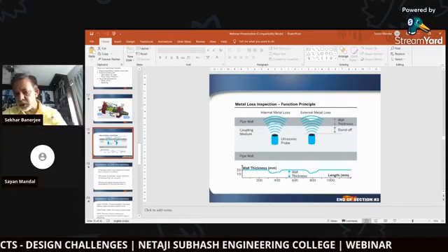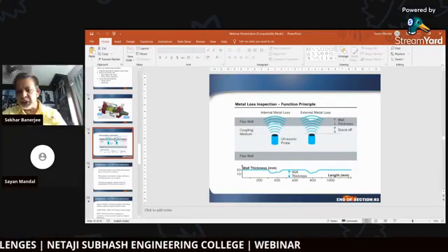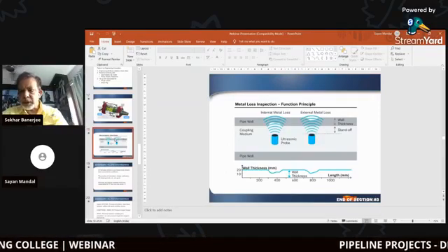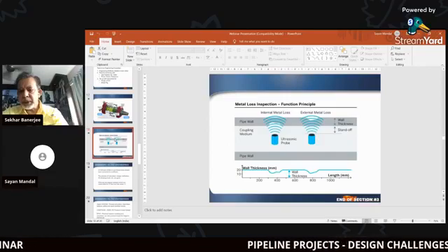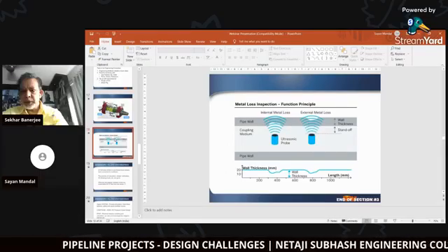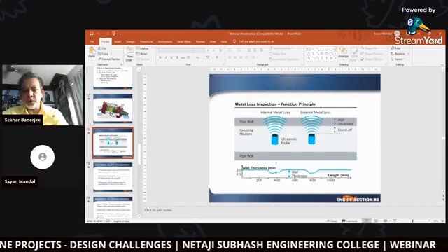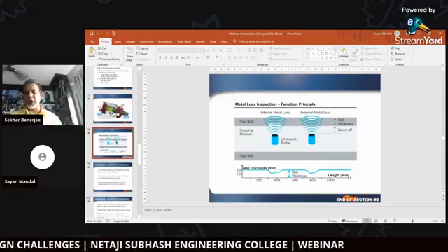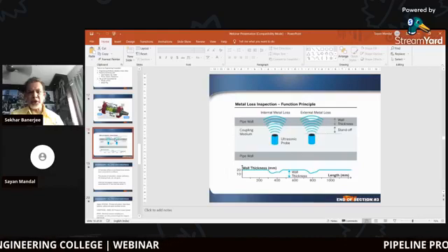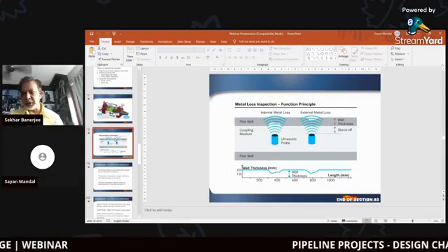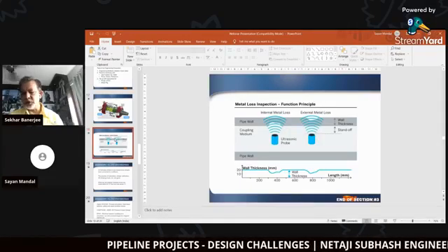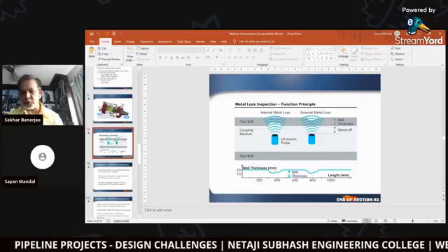Based on the previous slide, where I have shown you the odometer counting the distance, the pipeline maintenance engineer can plan whether he has to do a spot welding, or a reinforcement, or whether a major section of the pipeline has to be cut, for which you have to stop the pumps and drain it out. There are various ways of maintaining a pipeline. So that can be planned well in advance. It's a continuous monitoring tool. It is normally done once or twice a day.